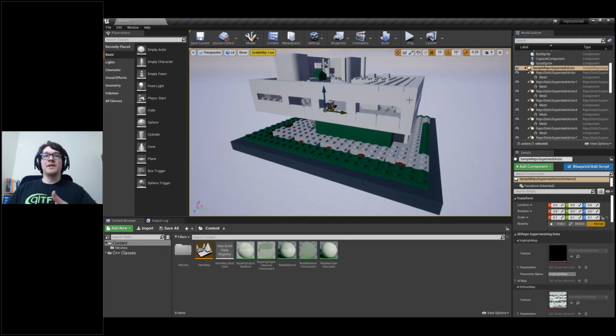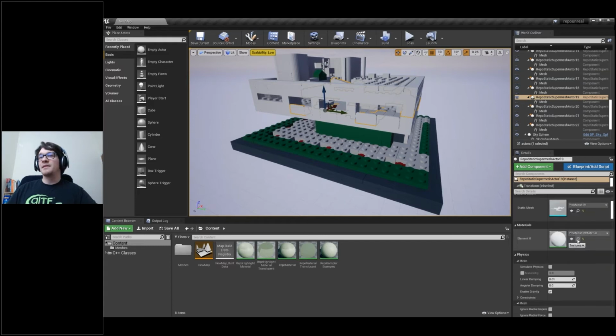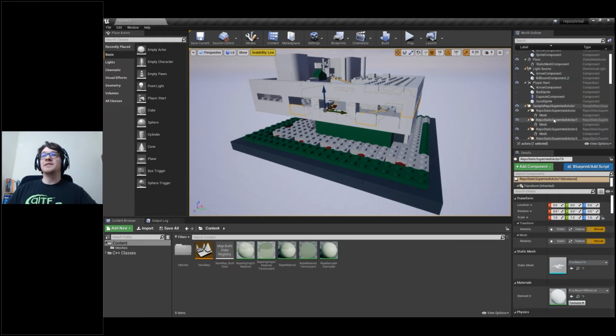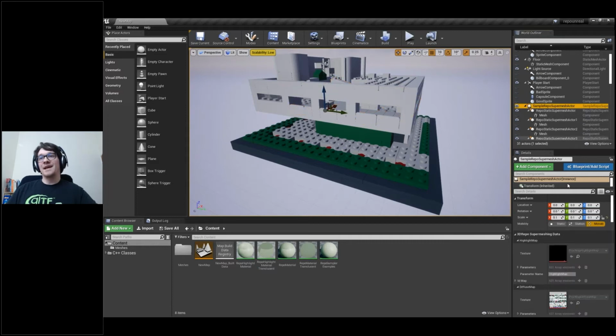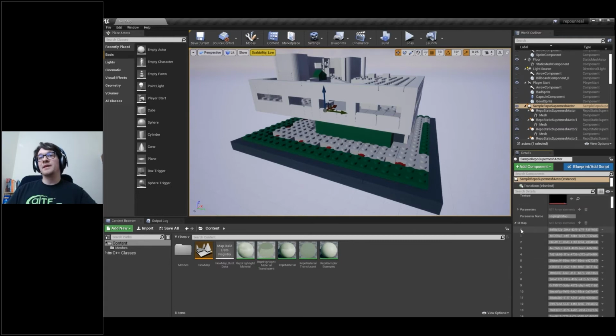The first one, the lowest level, is the data embedded in the mesh itself. These are, if you're interested, the UV coordinates, and these are pointers to object IDs. So they're just numbers that exist in the mesh, and these reference into a map which is stored at the top level on the actor itself. If I have show all advanced details on, I can see this property here, this ID map, which will give you the mapping between a simple number and this mesh ID. This mesh ID, this GUID here, is a unique identifier for the object throughout the entire 3D Repo ecosystem. You can use this within the plugin, and you can also use that same ID on the web to query information about that object.